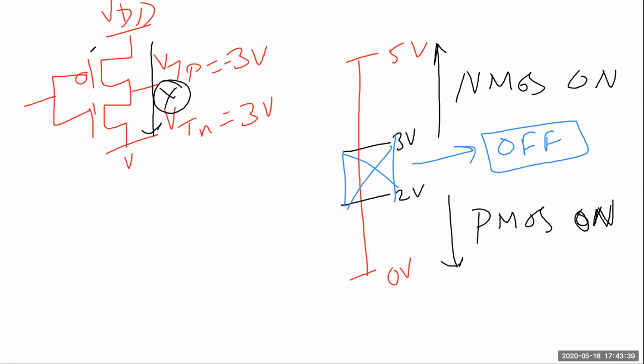Like I had explained before, the noise margin condition is that NMH plus NML is lower than VDD. That is only if VTN plus VTP is less than VDD. If it is not, then I think the noise margin will be higher, because in the first case, your input is considered as a load till you get to VTN, which is 3 volt, right? And then on the higher side also,